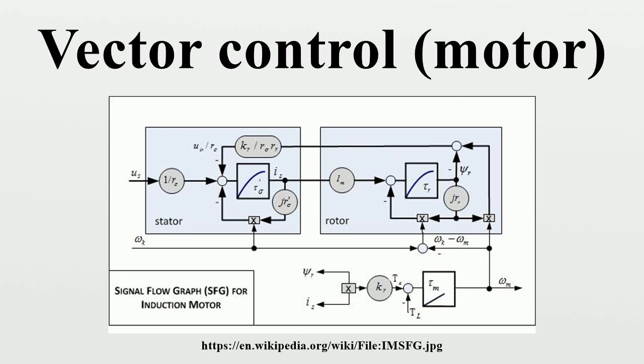4. The current vector is converted to the rotating coordinate system. 5. The D-axis component of the stator current vector is used to control the rotor flux linkage, and the imaginary Q-axis component is used to control the motor torque. While PI controllers can be used to control these currents, bang-bang type current control provides better dynamic performance. 6. PI controllers provide the coordinate voltage components.